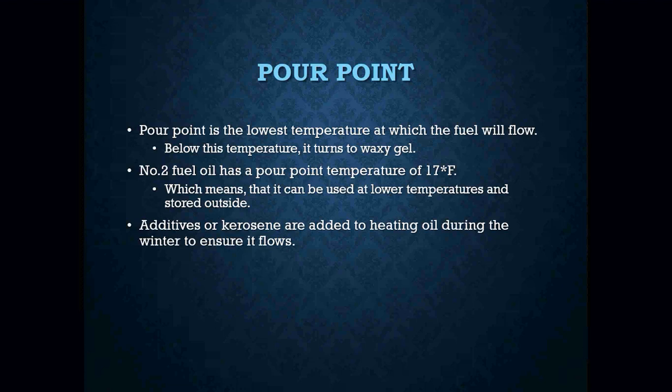You have cold flow improvers that are out there. Flow improvers are basically designed to lower the cold temperature operability limit of the fuel and to avoid wax plugging of the oil filters. Pour point reducers or anti-gels lower the temperature at which fuel gels or solidifies, and cold filter plug point reducers lower the temperature at which wax plugs the filter. So there's different ones that are out there.